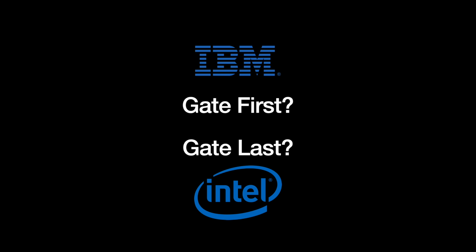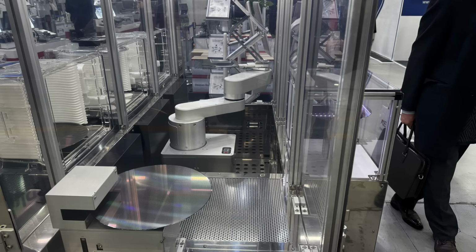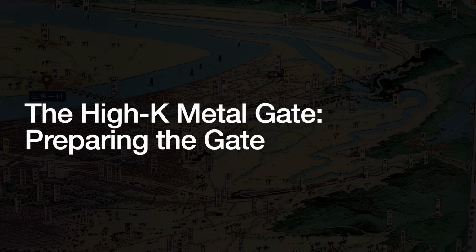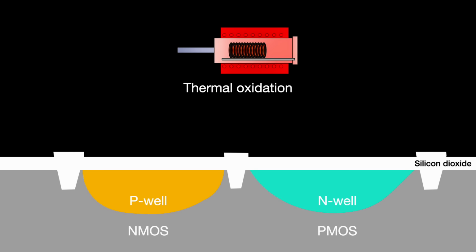It's called that because we produce the real transistor gate at the end. However, we still need a gate to be there to align the source and drain. So we build a sacrificial gate, a dummy gate. Let's do that. To start things off, we clean the wafer surface to remove any residual surface oxide. Basically, you should assume we're cleaning the wafer all the time, really. Next, we stick the wafer into the furnace again to grow a fresh layer of silicon dioxide with thermal oxidation.